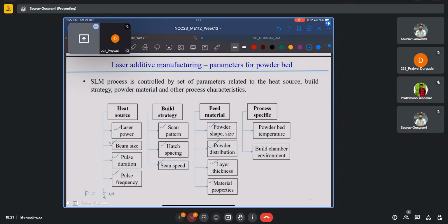And there will always be some process specific parameters which need to be accounted for, such as, in the case of the powder bed example, the temperature, if any, used for preheating. In electron beam melting, we know that there are two passes. The first pass is conducted with a diffuse electron beam, which simply sinters the powder particles on the bed, does not melt them fully, and preheats them to an applicable temperature.